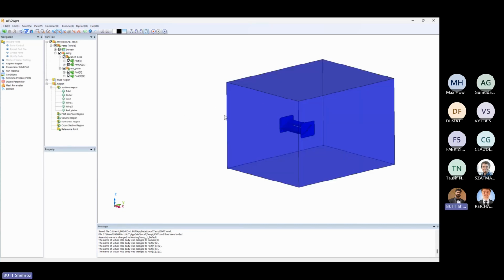So once this is done, your model will change from the initial green color to the blue color you can see here. Okay, so once we built an analysis model, we can proceed into the meshing stage. So in scFLOW, meshing is done in 2 steps. First, we create the octree, and then we apply the meshing layer. So with the octree, we basically represent the building block of our mesh, and it is used for the resolution of our mesh.